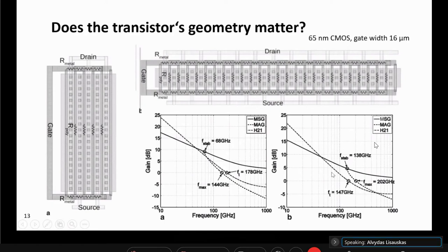And you know that in the very beginning I showed that Ft for this transistor can be about 200 gigahertz, yet it's only if you take a single small finger. Now, when we do oscillators, we have to make power matching. So we have to extract the power, and impedances should work. And so the practical impedance, for example, here is for a device with really long gate width.